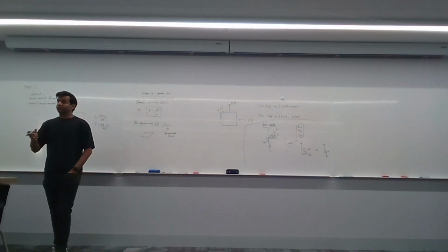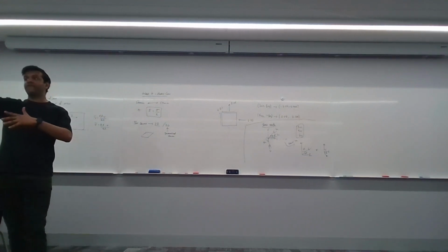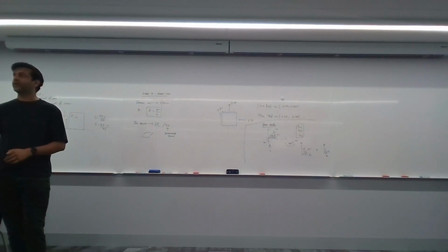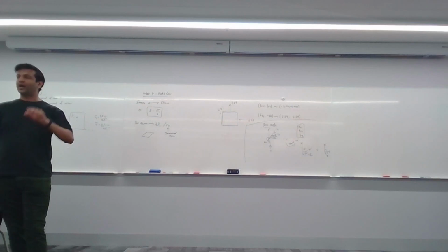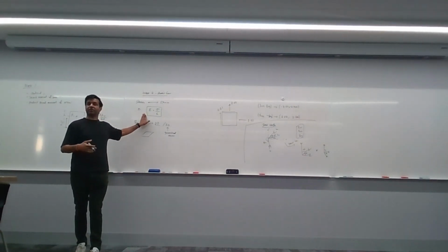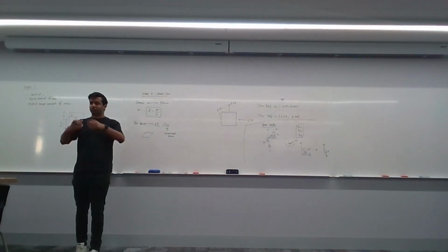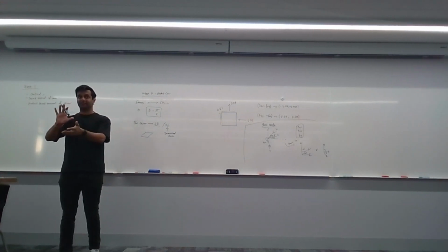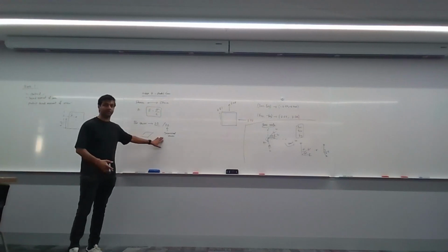You have the formulas with you, they're in the lecture notes. Basically, it's a bunch of formulas showing every single direction, x, y, and z, and tells you how to convert sigma xx to epsilon xx, and yy and zz. The reason why we don't use this formula directly just as is, is because for a 2-dimensional case, that's too simple. If you stress or strain something in one direction, the other directions aren't unaffected. They are going to be affected as well. And because of that, you have a generalized set of formulas here.